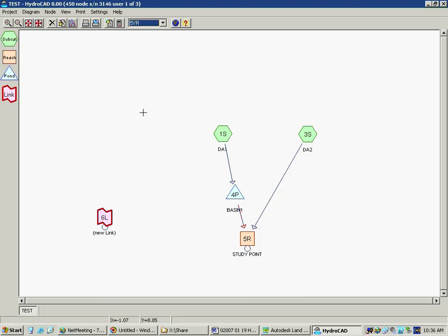As far as I understand, does everybody else? Yeah, I agree with that. TR55 looks at a shorter storm. It doesn't look at the entire volume of the hydrograph. I think it starts at some portion before the peak. It's more for looking at peak elevations, but what Mark is saying is right, it's the same methodology. It was a simplified version that sacrificed accuracy for your storm volume for quickness in doing hand calculations. If they really wanted to stick with that, you could probably set your storm duration not to start at time 0, but rather at the end of your duration, which gives you that full volume under the hydrograph.